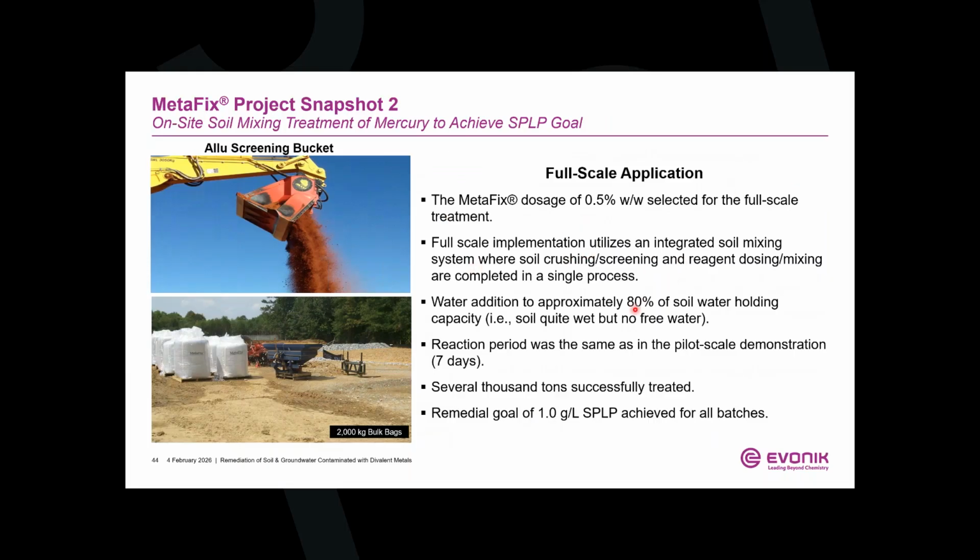The full-scale application involved treatment of several thousand cubic meters of this same mercury-impacted soil. 0.5% by weight of the Metafix reagent, added water to bring water content up to about 80% of the soil's water holding capacity. So the soil was quite wet, but there was no free water. We weren't creating a slurry. Reaction period was only 7 days, and all of that several thousand tons of this soil was treated to achieve the 1 µg/L, 1 ppb SPLP for total mercury in the leachate.